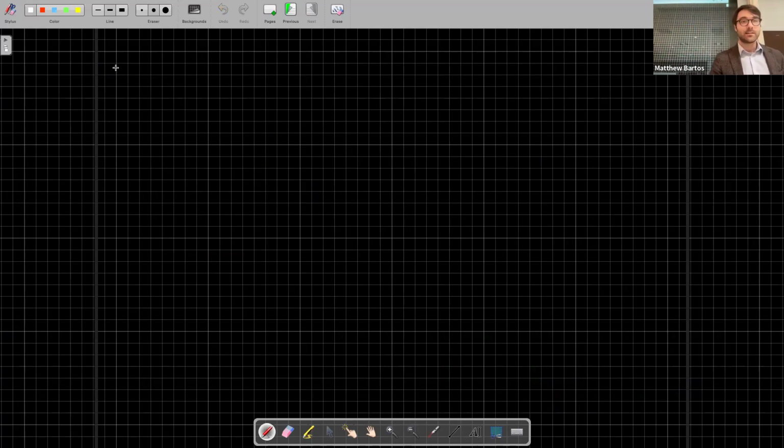So we have that the system head, HSys, is equal to HStat plus K times Q to the 1.85. We can substitute in our known values. So the static head requirement is 10 meters. That is the elevation difference between the two reservoirs.